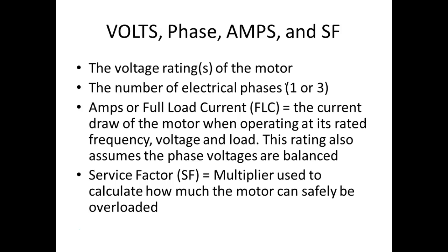This doesn't happen sometimes in industry, where they put more load on one phase than on the other. This is why when we hooked up our transformers, I wanted y'all to rotate. Some of y'all used phases 1 and 2, some used phases 2 and 3, some used 1 and 3, and that way we try to keep our phases balanced. If we measured those 3 voltages from phase to phase, they should all measure the same. If they don't, my motor might behave differently on one phase or pull a little more current on one phase than on another. So this all depends on balance.